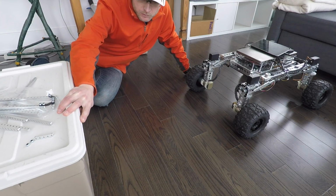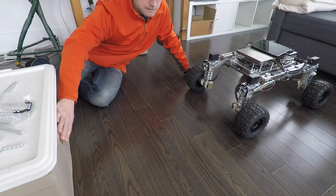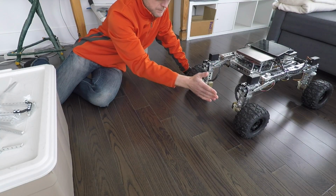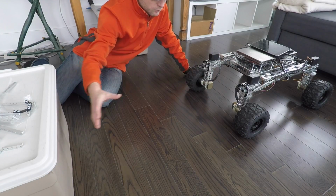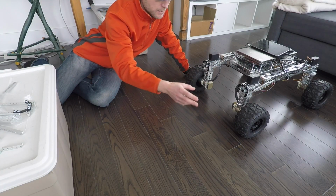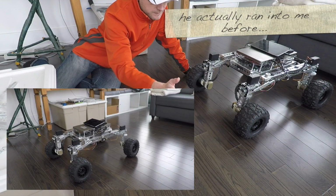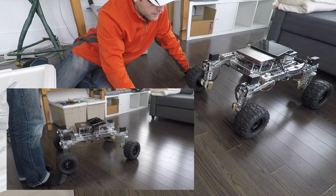So I've positioned this storage box here just to give us a movable object, because I suspect that ROVer is going to actually hit it, because I probably have to tweak the sensor sensitivity. Right now I have them set at about this distance here, but I think that isn't actually a practical value or distance when he's actually rolling forward, because he has momentum, and it takes a few fractions of a second for him to actually process that information before he actually does come to an actual stop. So the actual point at which we want those sensors to trigger might be somewhere farther away. I'm not sure, but it's a bit of trial and error until we figure that out.